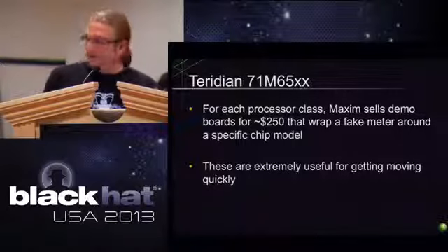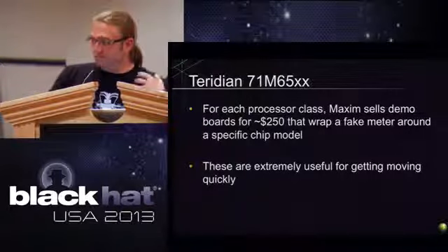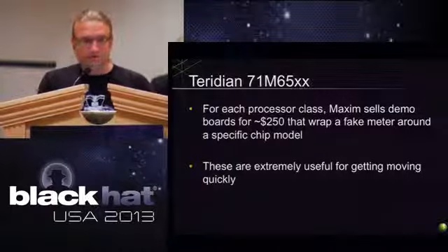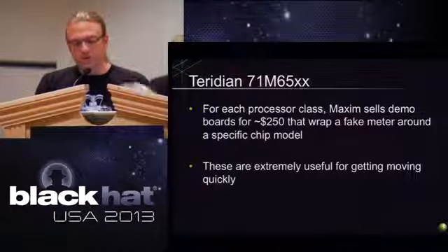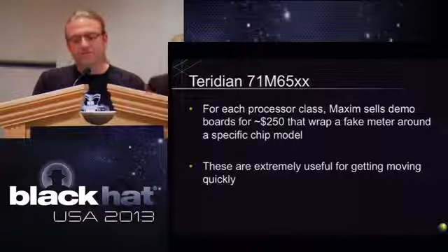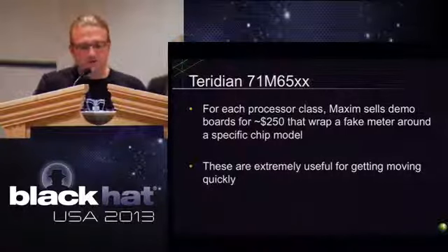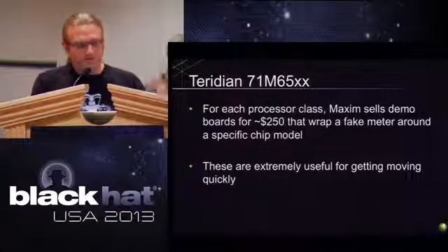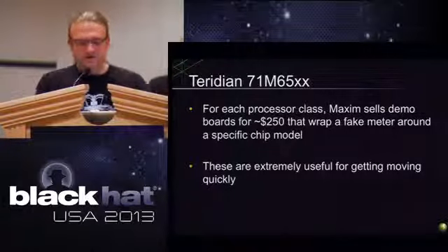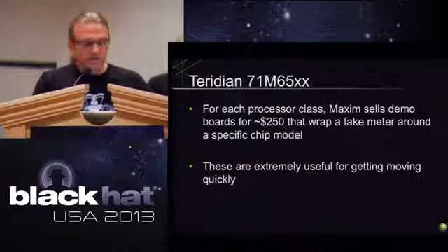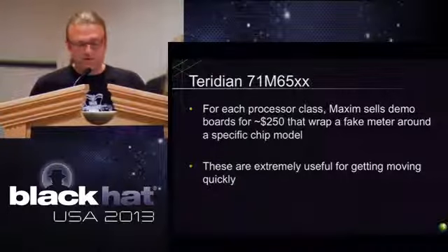A couple more pro tips. If you ever get into the space, if you ever start poking in a SoC in general, Teridian is wonderful about this. They have dev boards where they're trying to sell big vendors millions of these chips to start building hardware with. So they make a demo board that has great open source code. It's kind of open source hardware. They're relatively cheap, so they're great because the whole chip is broken out completely already.